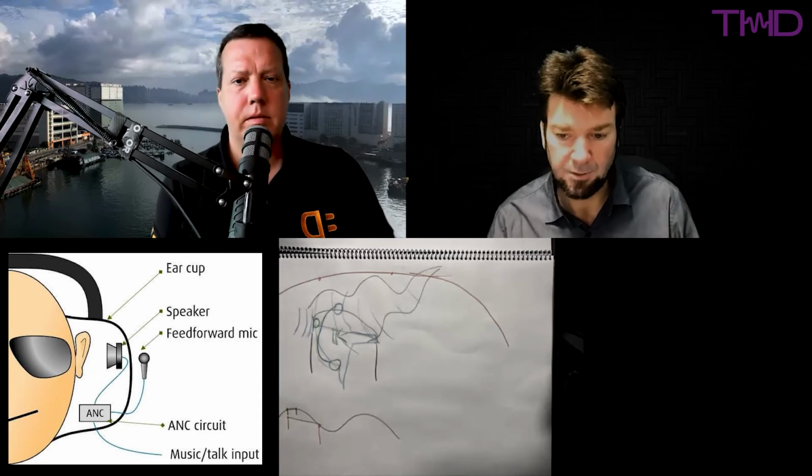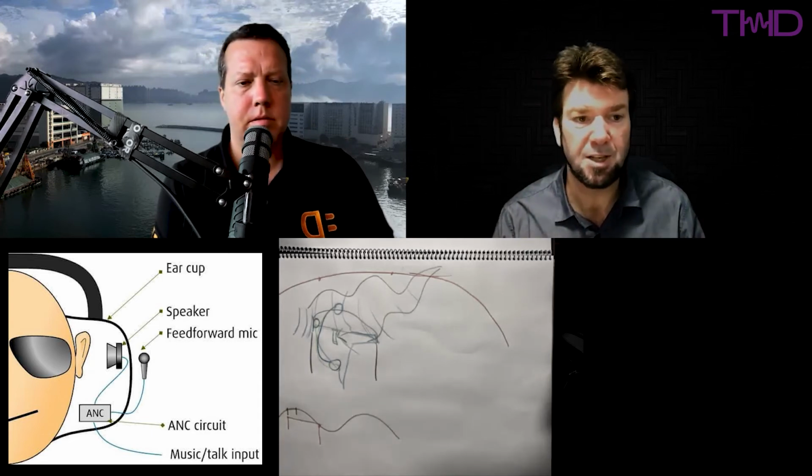I was going to come back to that and just say for feedback, you're not trying to match that transfer function. You're trying to produce as much gain on the signal as possible without going unstable. So there are two quite different philosophies, and when people say it's "noise cancellation," it's not. Except for the fact that they are trying to use destructive interference, or adding opposite sound waves together, there isn't any other similarity really in terms of the design principle.